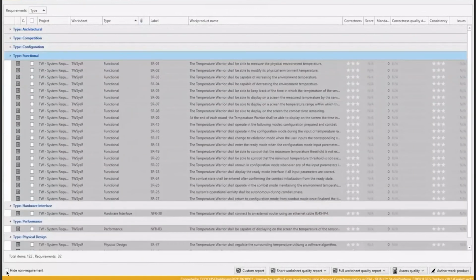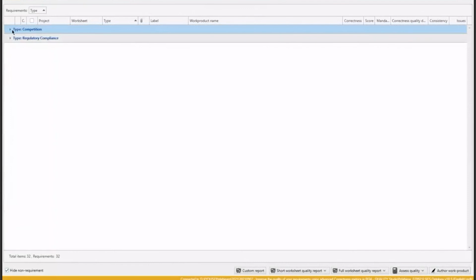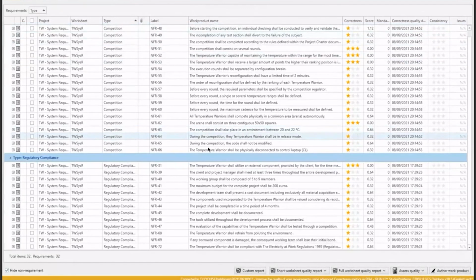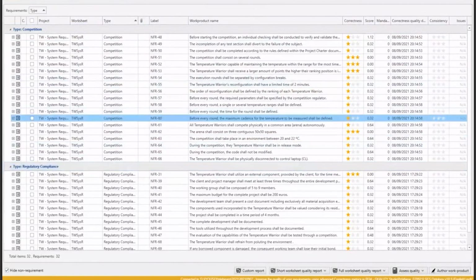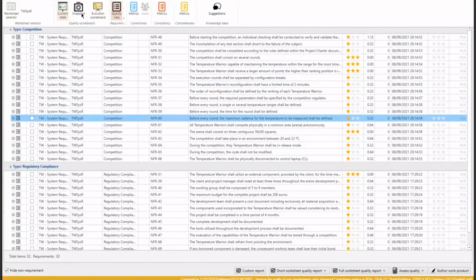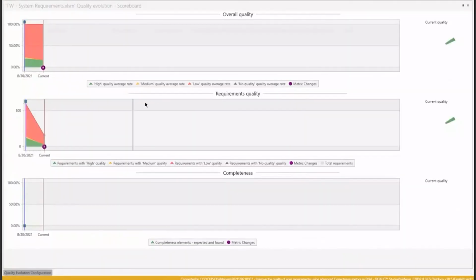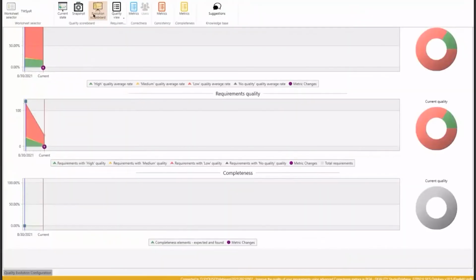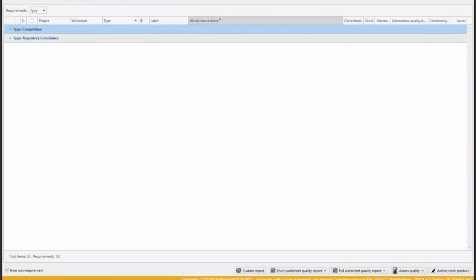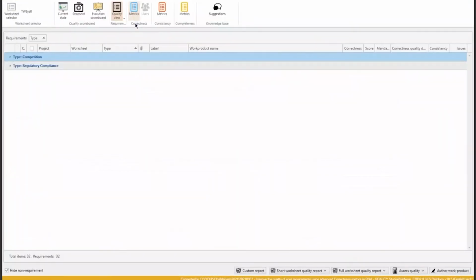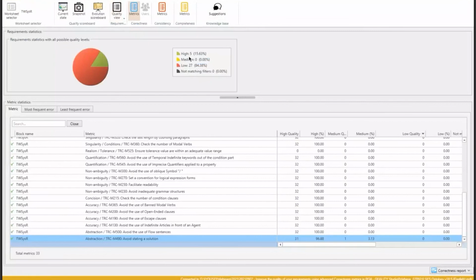And you can hide the non-requirements, which keeps only the two groups necessary for your scope. And then, of course, all the results should consider the requirements that you filtered. So basically, if I go to quality control and to the view or the metrics here, it should produce a new assessment only with the filtered requirements. So it refreshes the statistics based on the filters.